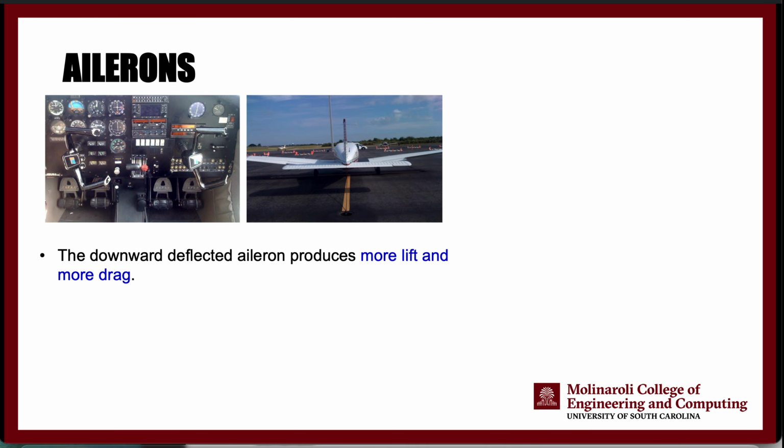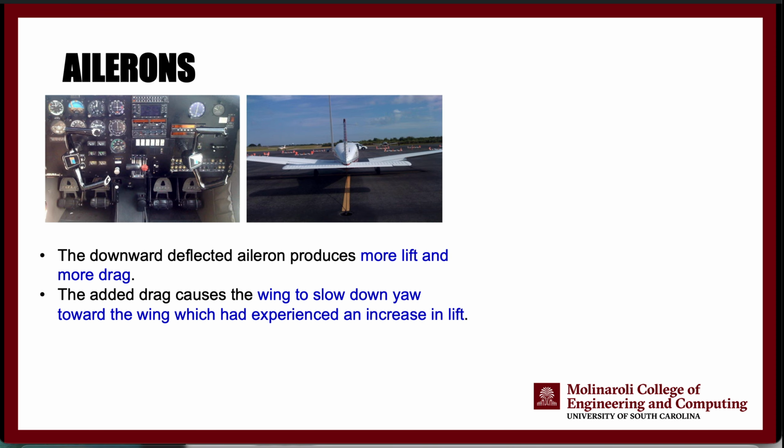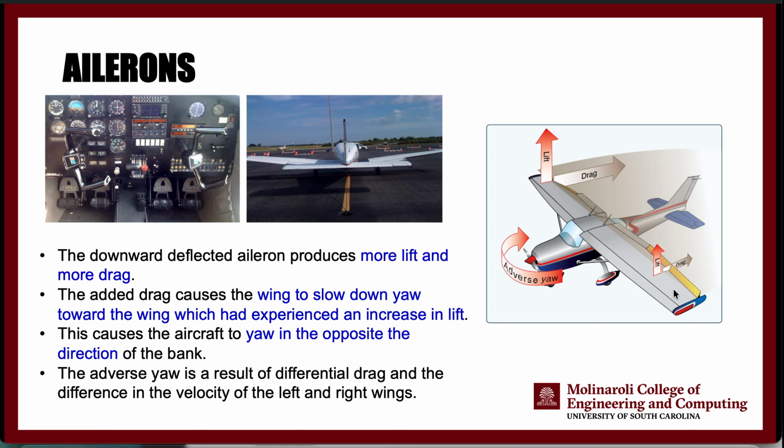How do the ailerons generate the lift? It essentially is pretty simple right here. When you're creating a negative camber right here, you see the camber is in the upward direction. This is going to create a negative camber, which means it is going to reduce the lift in our desired direction. On the other side, we are going to increase the lift in our desired location, right? So we are creating a negative lift here that is going to counteract the lift generated by the whole wing. So more force here, a bigger force here, a smaller force here.